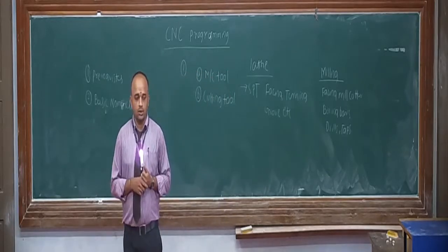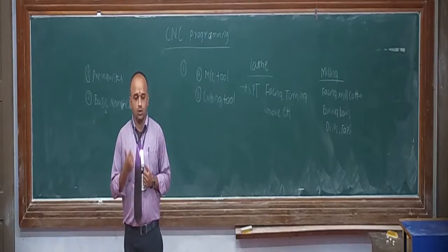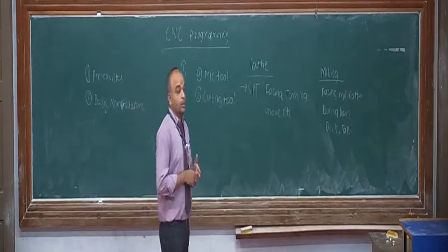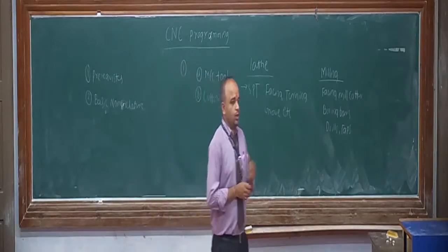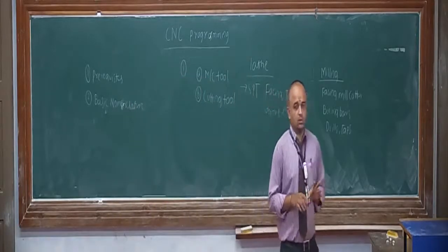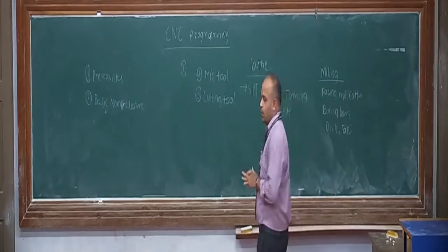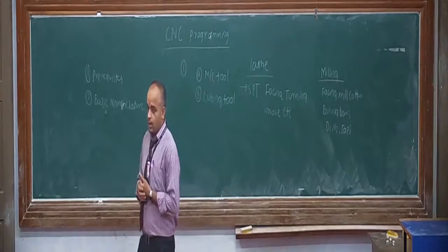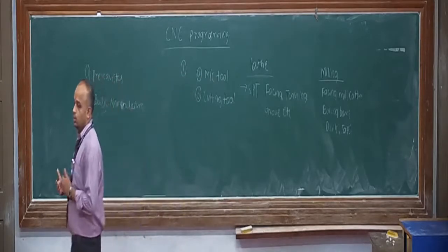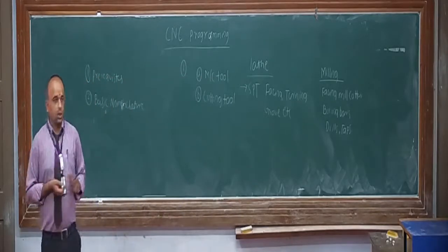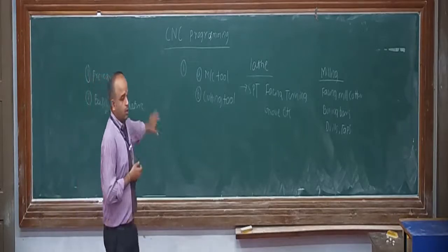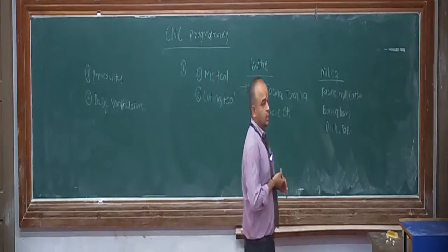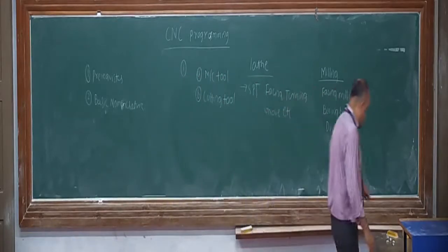Otherwise, every time the operator has to change the cutting tool and do the operations, and your setup time increases. Important is, for any production, we have two things: one is processing time and one is setup time. Always remember that setup time should be as low as possible, so that the processing time is more, and by which we can produce a component in a very short duration of time.